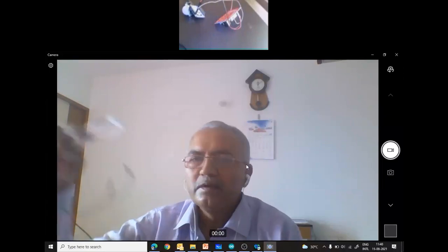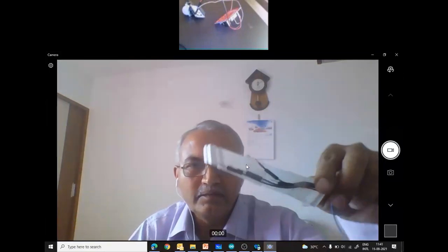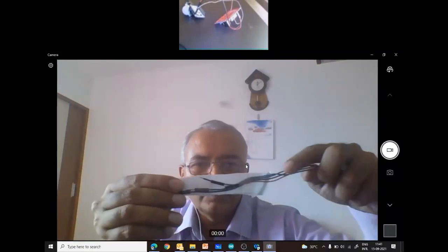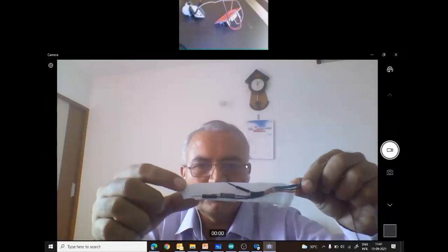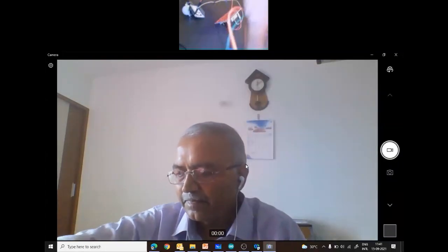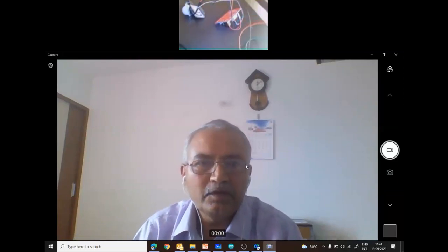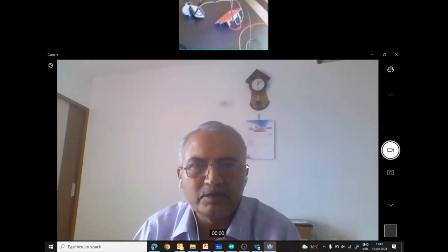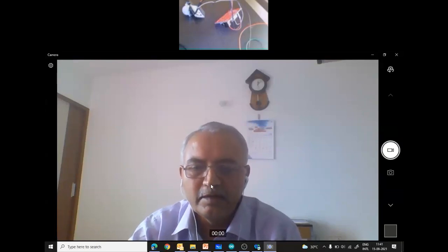This is prepared like a level sensor. Different wires are put at different distances and we can insert it into the tank. So it's a very simple homemade water level sensor. So we can use different sensors, which are basically transducers, that get the physical quantity, convert it into an electrical signal, and then we interface it with our hardware.